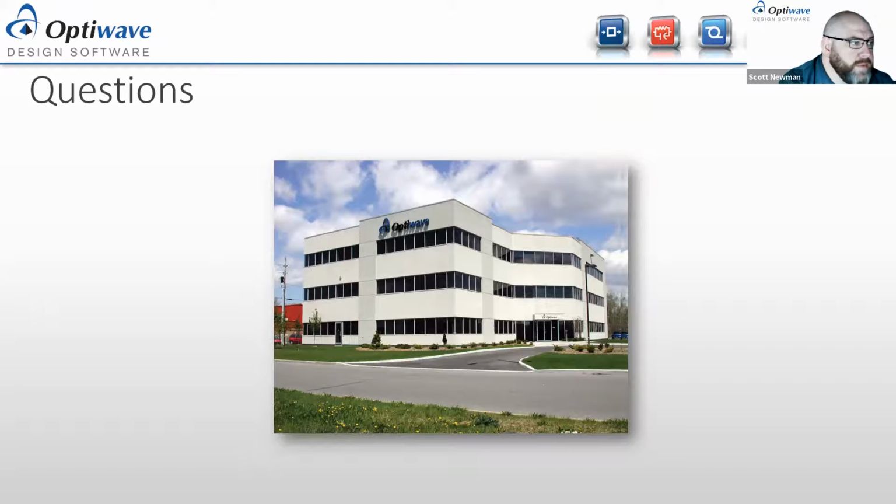I've got a couple of questions, Gabby, as well as a couple others, that comment on simulation duration. Fundamentally, it's difficult to say how long the simulation takes because it's going to very much depend on the resolution you require for running that simulation and the size of it. It's not the fact that we're running the source from the cavity center that's dictating the simulation needing to run for a long time. It's the fact that there is a cavity. So you want to run the simulation long enough so that you're getting enough information in there. I know it's a bit of a wishy-washy answer, but it does highly vary depending on the designs.